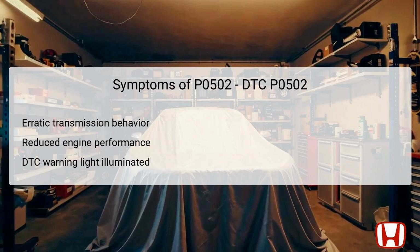When DTC P0502 is triggered, drivers may experience a variety of symptoms during vehicle operation. Commonly reported issues include erratic transmission behavior, which can manifest as unanticipated shifts or hesitation during acceleration. Additionally, engine performance may suffer due to incorrect data being sent to the TCM, resulting in a less responsive throttle or stalling conditions.